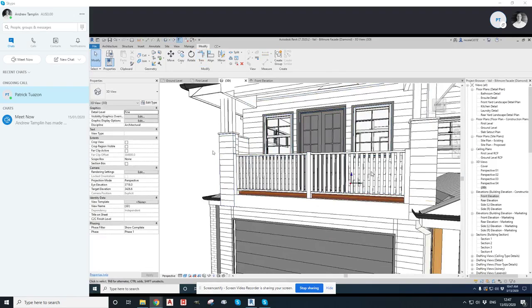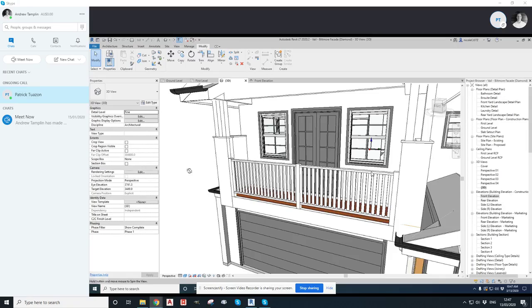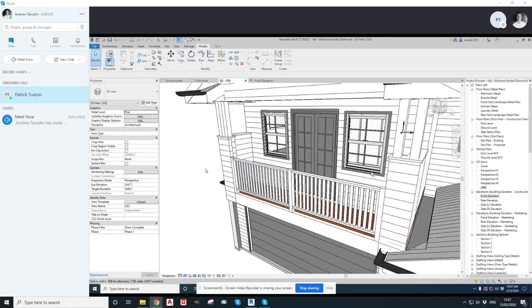That was probably very long-winded. I'm sorry. Basically, what you've just done is create 2 railings. Because the railing is automatically set to have a post on either end, we just needed to work out the center point. Then you put the 2 railings together and make sure that post is sitting on top. Technically there's 2 posts right there because you've got 2 railings, but because we've got them sitting on top of each other, we've just made it look like there's 1 railing, which is fine to do for now.